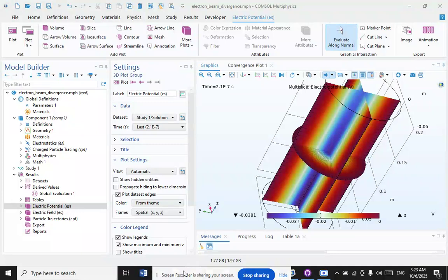The third one is as the beam divergence is decreased, full penetration keyholes are more likely to form. However, in the transition from partial to full penetration, these keyholes are more likely to be unstable. The fourth one is significant Mn and, to a lesser extent, Cr evaporation is predicted for the electron beam welding of SA 508 ferritic steel.